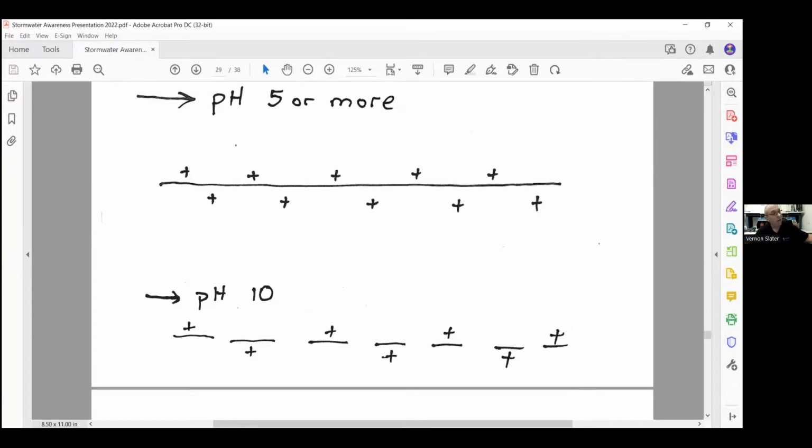And then the next question was about that. It says, what's the difference between a coagulant and a flocculant? So a coagulant is a substance that causes particles to clot or bind together. Typically, this is done using a coagulant of opposite charge to the target particle. The flocculant is added to the suspension of coagulated particles to form larger particles that can gravity settle out and be removed in filtration.